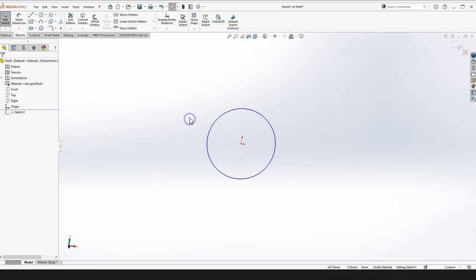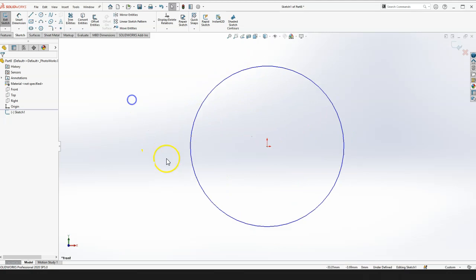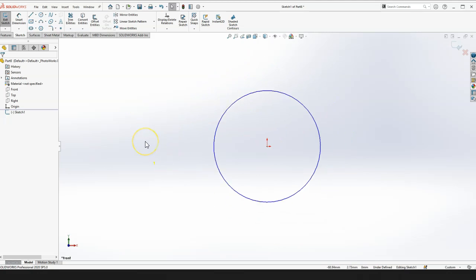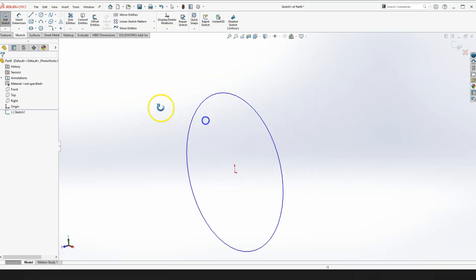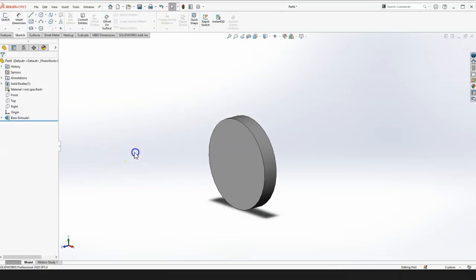And press space bar and you get all the orientation views, and I'll teach you about the orientation one more time. So let's rotate this model really quick. Let's extrude that. So my shortcut, if I press S, now I have all these features. Let's say I want to extrude it. Click on that, just extrude like 10 millimeters or so, right?